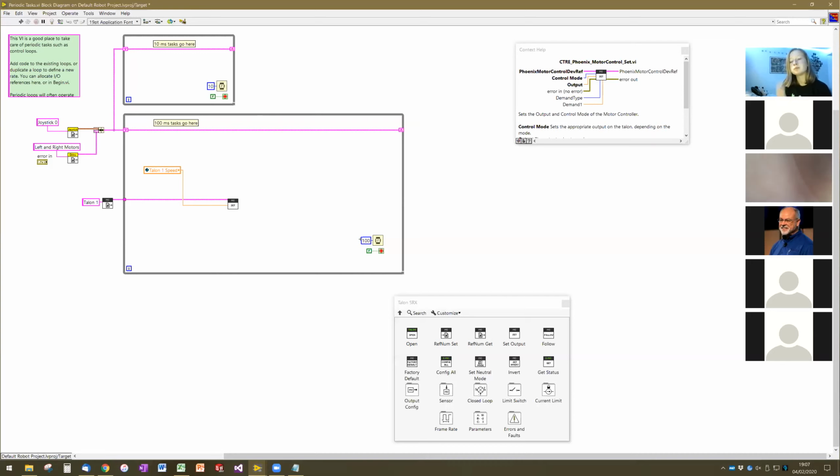It only sends data when data change. We've solved that problem on our end, and there's a session that people have voted for that will cover this. We've solved it by having another structure around this block that checks to see when this value changes and only sends new values to the CAN bus when that value changes. And so that's how we reduce our CAN bus utilization.